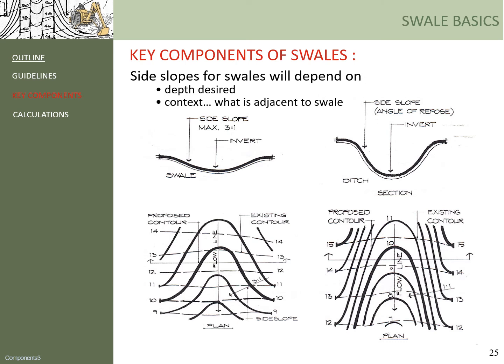Over the years, we have found that the concept of the depth of the swell tends to be easy to understand in the section view, right? Essentially, the depth is the elevation difference between the top of the bank and the invert along the center line. But it's fairly difficult to understand what depth means on a plan view, and we'll explain that in more detail with the next slide.